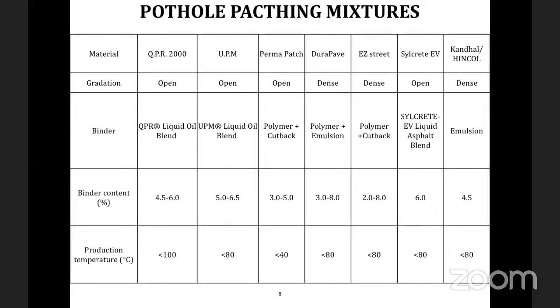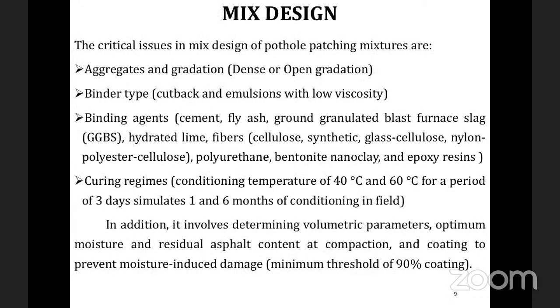Hot mix is the normal mix which we prepare in the HMA plant. After this, we will see what the mix design criteria are, and how these pothole patching mixtures can be designed. To know that, we have to see some of the critical issues. So what are the critical issues in the mix design of the pothole patching mixtures? One is aggregate gradation. Next is the binder type, and which type of binding agents are used, and what the curing regimes are. As this is a cold mix or a ready-made mix, it requires some curing regimes.